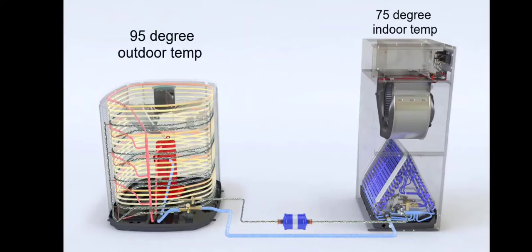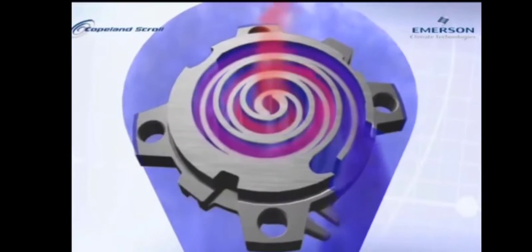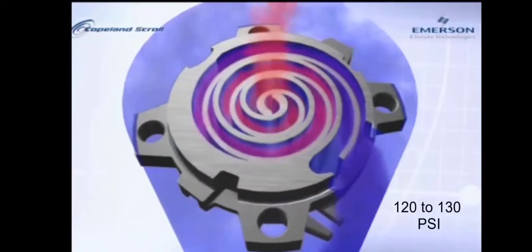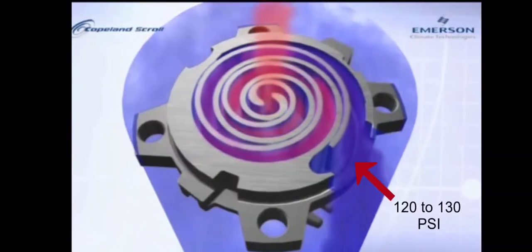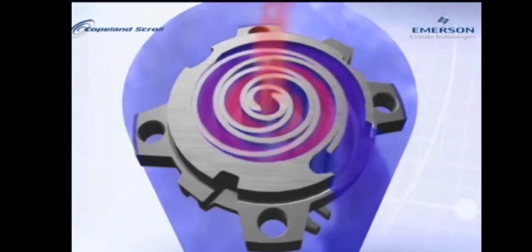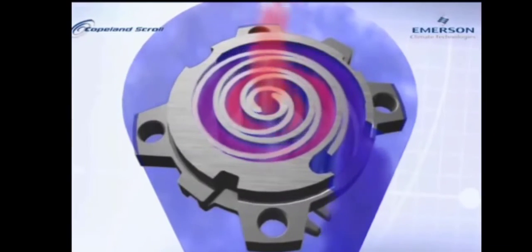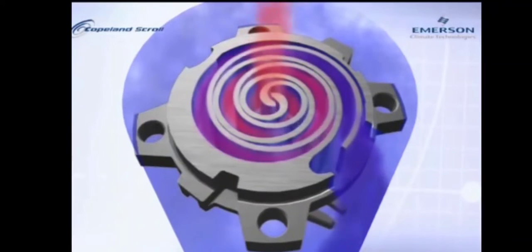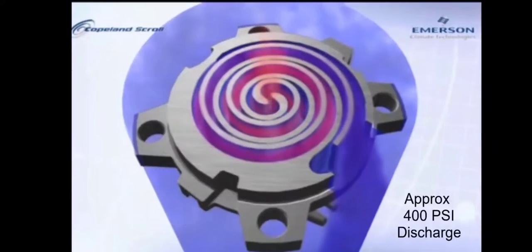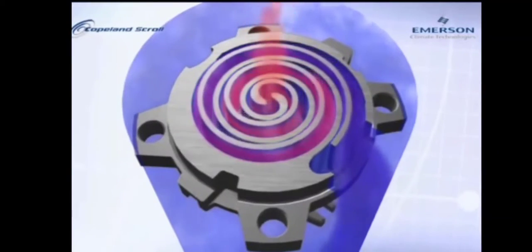It compresses vapor refrigerant. And in the animation here of a scroll compressor, you can see the vapor refrigerant, that's probably around 120 pounds of pressure, entering through that large outside ring of the scroll plates. And as the refrigerant flows through the plates and towards that smaller center area within the scroll, the refrigerant becomes more and more compressed, and it exits the compressor, probably close to 400 pounds of pressure in our example here. And this increased pressure correlates to an increase in temperature.